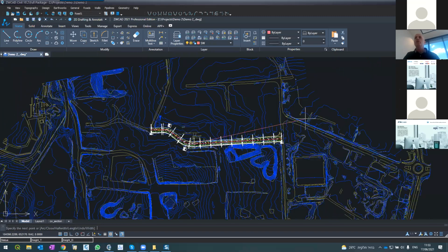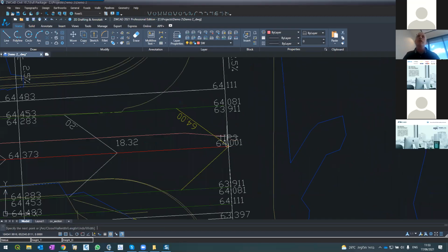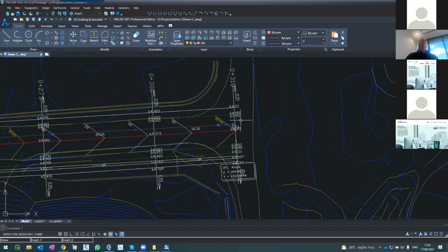And from here, it's straight to the end, but of course, I will have to create manholes, let's say, each 40 meters for each plot that will come. We said we are doing land development to the left. So let's say 40 meters, 40 meters, 40 meters, 40 meters, and another one here in the junction. Good.